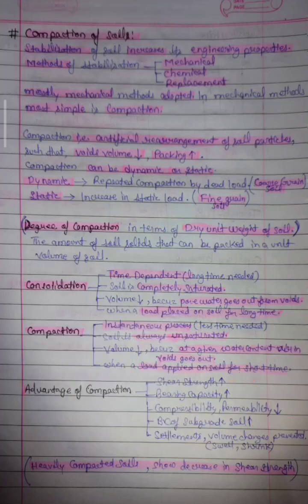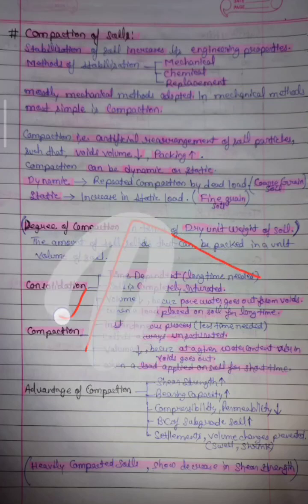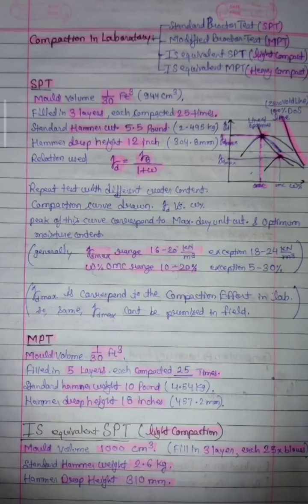Now heavily compacted soils show a decrease in shear strength. So compaction is good, but only up to a certain limit. After it, the shear strength will decrease. So over compaction is not good.